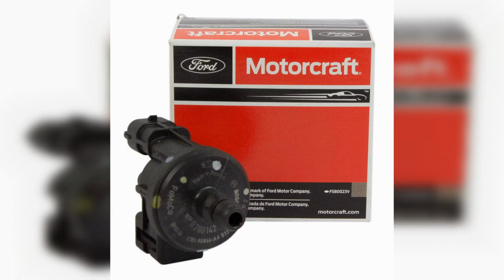P0496 on various brands. Although it can affect any vehicle, regardless of manufacturer, the P0496 code often occurs on GM vehicles, Chevrolet, Pontiac, Dodge, among others. On Asian car models, such as Honda, Hyundai, or Mazda, this code may mean high EVAP purge rate, which means the same thing. Although EVAP systems in general date back to the 1970s, modern enhanced systems appeared in 1994 but became ubiquitous on passenger cars and light trucks by 1997 with OBD2.